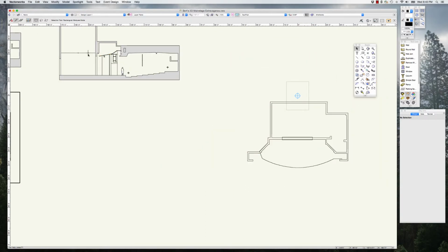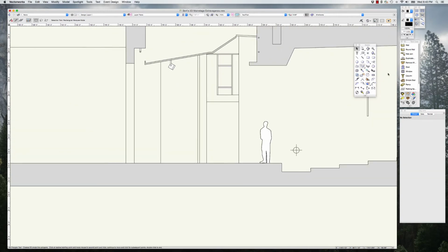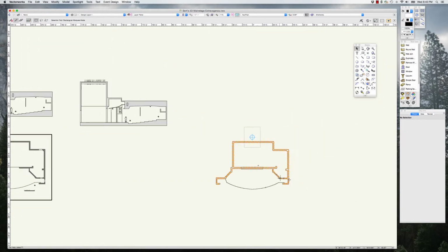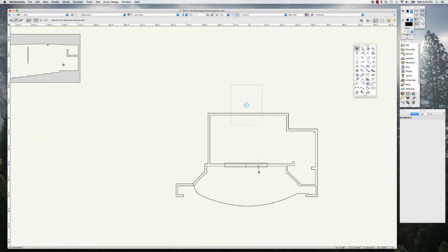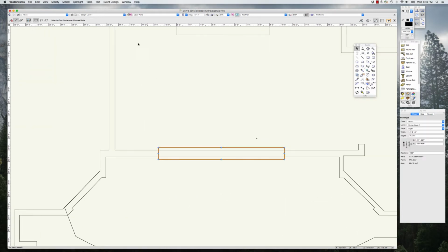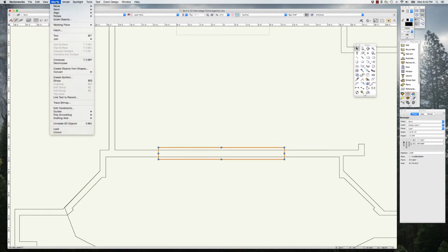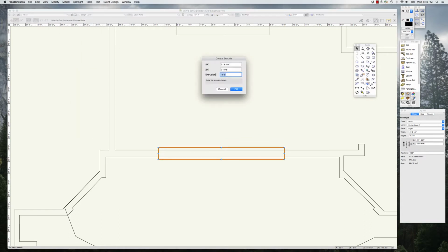So now I need to determine how tall the proscenium is. I'm reasonably sure it's 13 11, but let's see what our drawing says. Our drawing says that it's 13 10 and a half, so I'm going to call it 13 11. That's close enough, because who knows if this drawing is accurate, and I'm reasonably sure that we've measured the proscenium at 13 11. So what I'm going to do now is extrude this 13 feet 11 inches. Model, extrude, 13 feet 11.